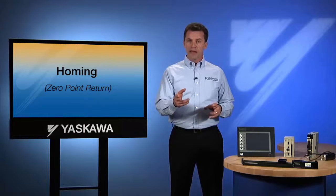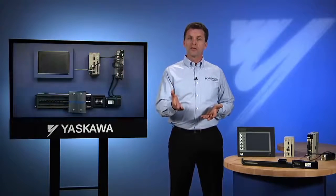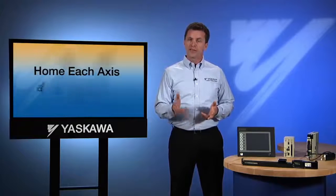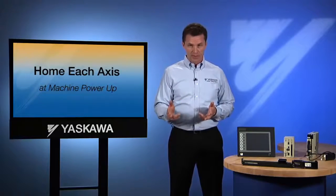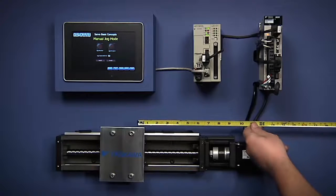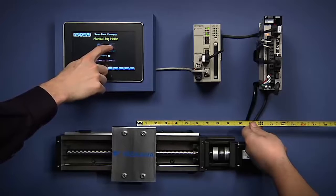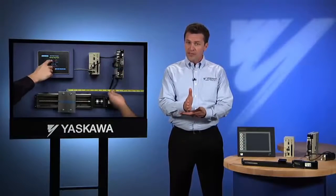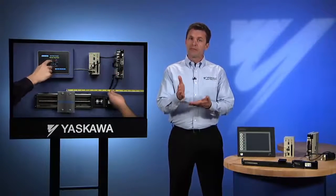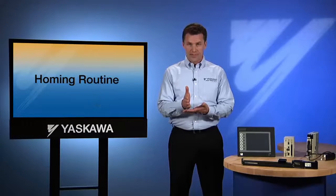To reorient an axis that may have been moved while the power is off, the controller needs to home each axis every time the machine powers up. A very simple way to accomplish homing is for the operator to visually align the axis to its 0 position. In actual practice, however, most machines rely on a fully automated sequence called a homing routine.